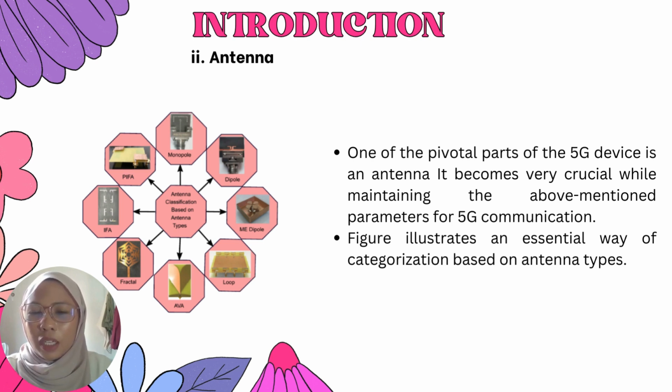Second is the dipole antenna. It is made of two straight microstrip lines of length each, with the feeding given between the two microstrip lines. As a result, the overall length of the dipole is a half wavelength. Third is the magnetoelectric (ME) dipole antenna. A planar electric dipole and a parabolically shorted planar magnetic dipole comprise this antenna. The magnetic dipole receives its feeding from the substrate bottom side.